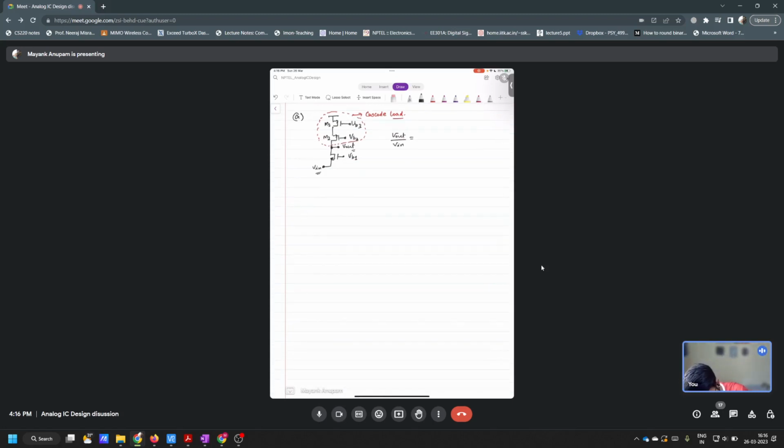So anyway, let's forget about this. Today I want to explain to you one of the methods to find the small signal gain. One method is that you simply solve the whole circuit between input and output, by making it small signal equivalent, then writing KCL and KVL, and finding the relation between V out and V in.